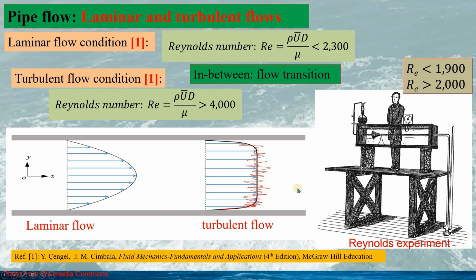Therefore, for the pipe flow, we might have a question of how we can express the velocity. In laminar flow, we can use U max to represent the pipe flow velocity, since U max is a well-defined value. But for the turbulent flow, the variation is very time-dependent, and the U max would happen in different places. So U max is not a good number for the turbulent flow.